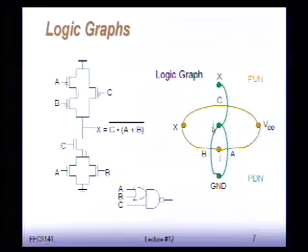And you can do the same thing for the pull-down network. And now there are some mathematical techniques: it turns out that you can find what is called the Euler path on this graph, which is a path that visits all nodes, taking every edge only once. And each of these Euler paths corresponds to an ordering of the inputs that gives you a multi-finger device. Okay. Of course, for a given gate, it can be that there is no Euler path.